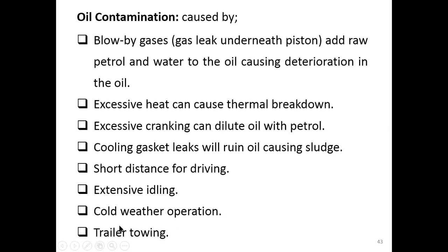Towing is also damaging to the oil. It damages the oil because of what? Under towing conditions, we have a low flow velocity of the lubrication oil, which is not high enough to perform the lubrication, or maybe we don't have any if it's under tow. So the velocity is very important. Okay.